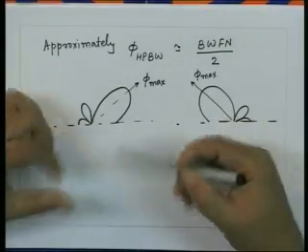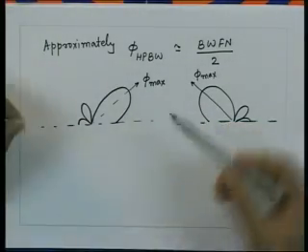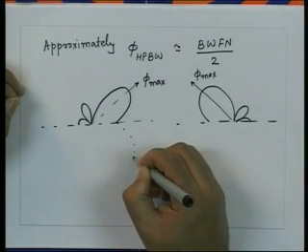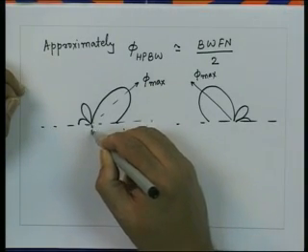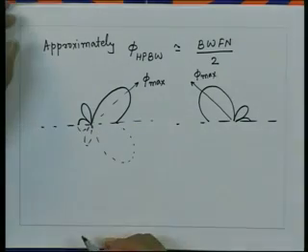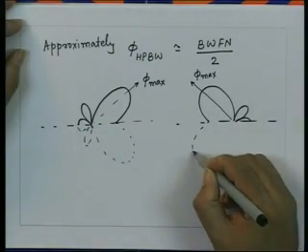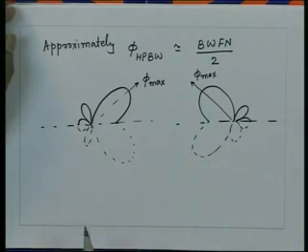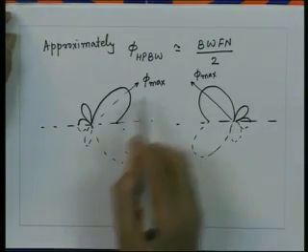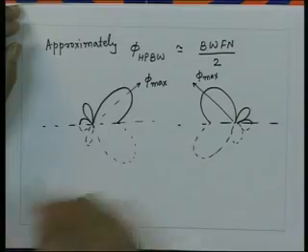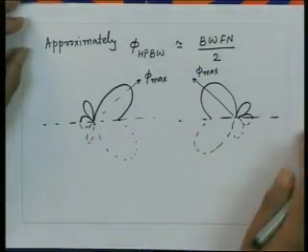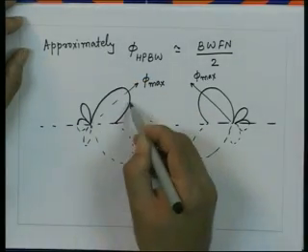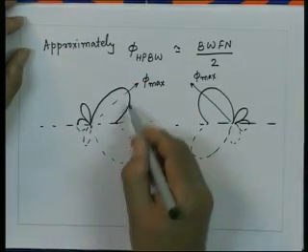Since the radiation pattern is a figure of revolution around the axis of the array, essentially if I draw that, it will look like that. The same will happen here, like this. Since the range of phi is from 0 to pi, the null corresponding to this one is visible, but the null on the other side of the main beam is not visible in this case.